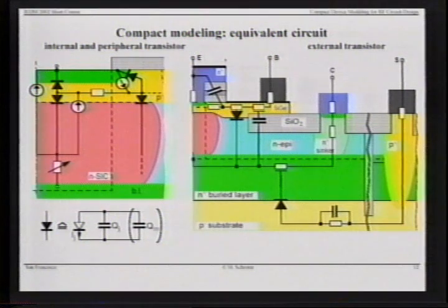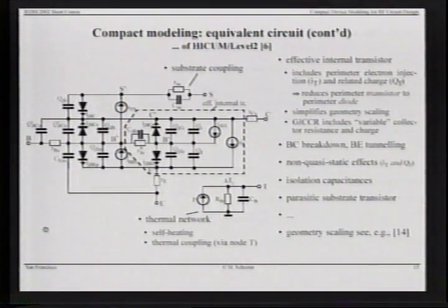For instance, spacer capacitances, distributed base resistance, parasitic base-collector capacitance, a substrate with a typical simple substrate network and a capacitance, etc. For not too high frequencies, we can lump many of these elements and come up with something that looks a little bit simpler but still pretty busy, and this is a typical equivalent circuit for the modern bipolar transistors, be it VBIC, Mextram, or HICUM. It's pretty busy and pretty difficult to understand for designers.